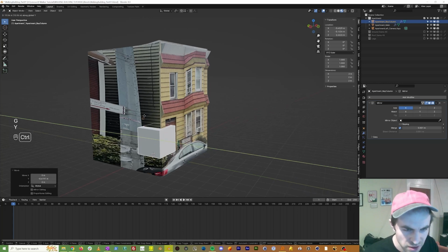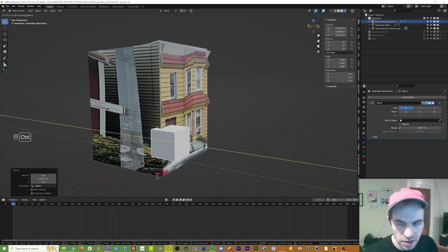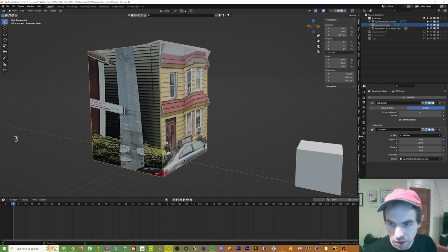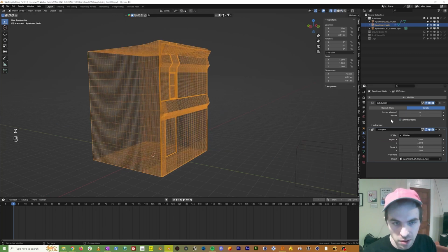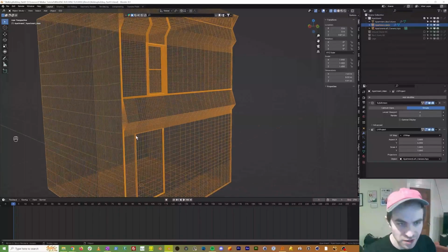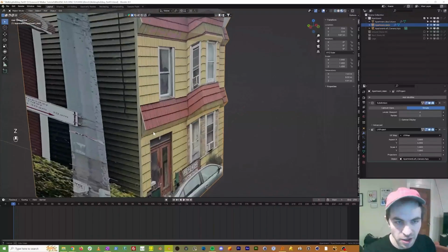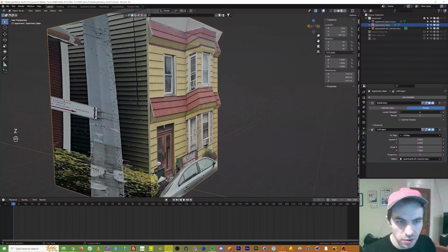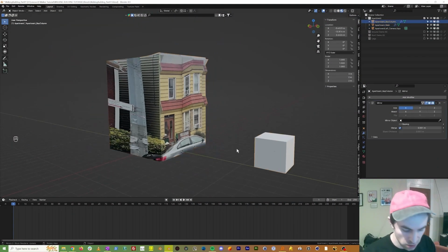If you're having trouble with the snapping, it's probably because we have so many subdivisions. You see, in reality, this is what our mesh looks like. So there can be a lot of detail that it's trying to snap to. I think at this point we can start reducing this a little bit. Let's put it on 2. That'll help.